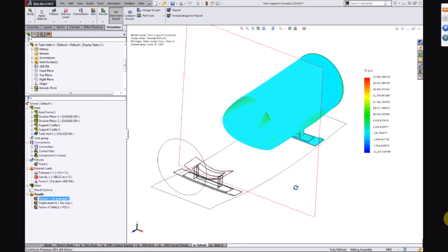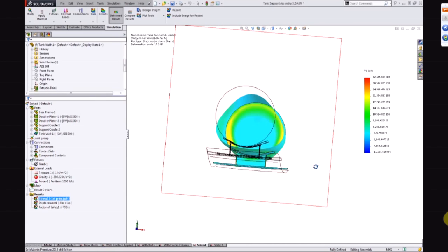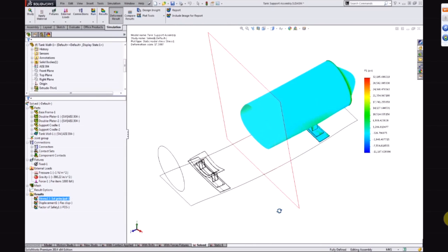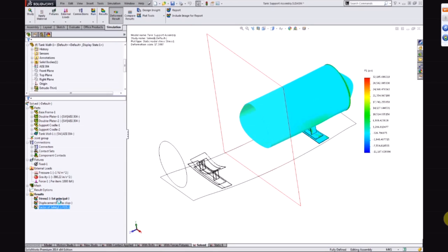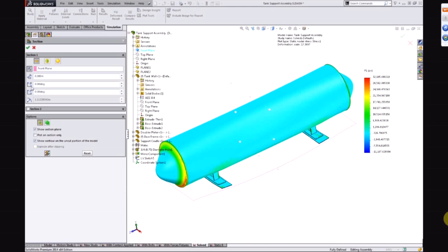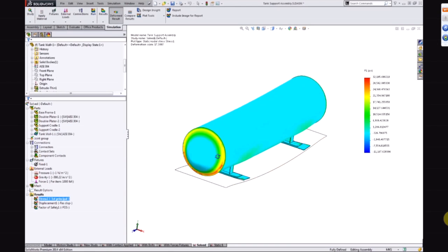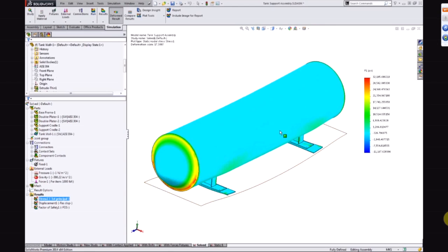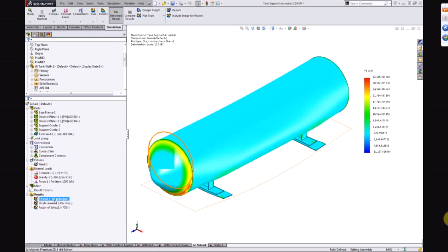one thing that always gets me is that it took me forever to realize: if you have sectioned something and committed to it, it's not immediately apparent how to get rid of that section. I don't know if anyone's ever seen that. The trick is go to section clipping and then click the unlabeled button at bottom left to turn the clipping off. For a couple of years, I was recreating a plot if I did that, so I couldn't find the switch.